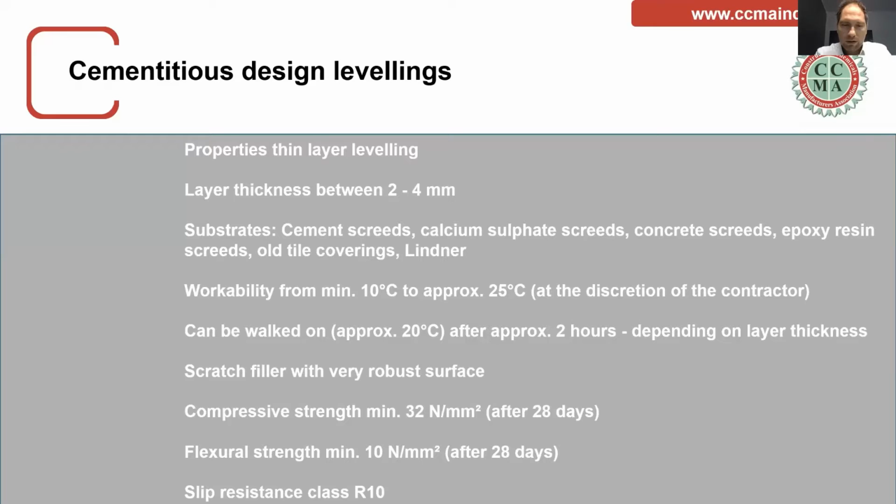Here also are used these fast setting cements, and because of the thickness from approximately 2 to 4 millimeters, the drying time is shorter and you can walk over it after 2 hours. The slip resistance, because of using a scratch technique, is more or less R10 or higher.